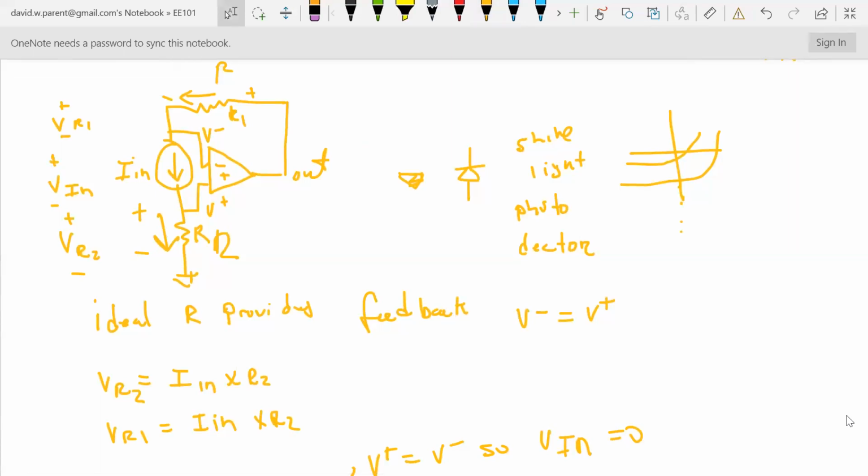All diodes can be LEDs or photodetectors. They just might be really bad at it. Okay, so silicon does not emit a statistically significant amount of light, but it can act like a solar cell. It can act like a photodetector. Okay. Alrighty.